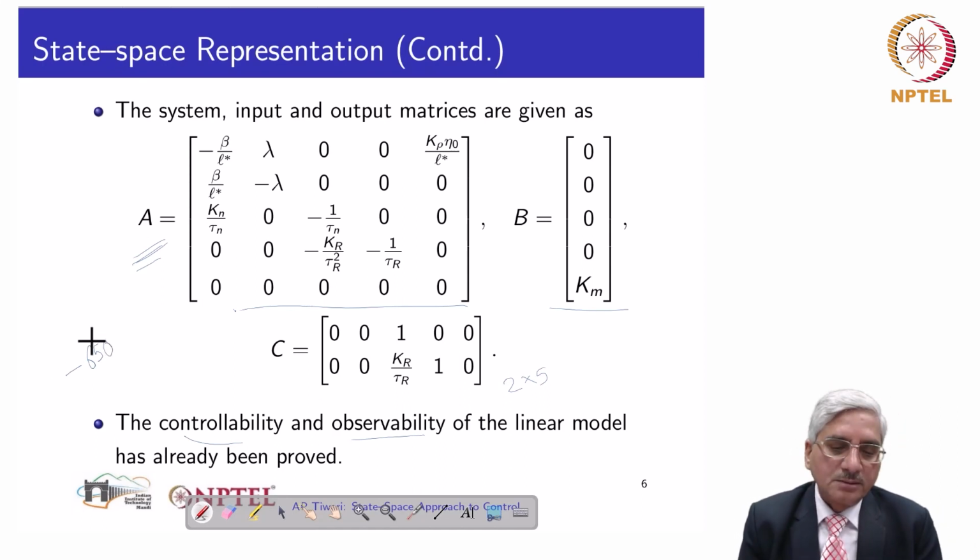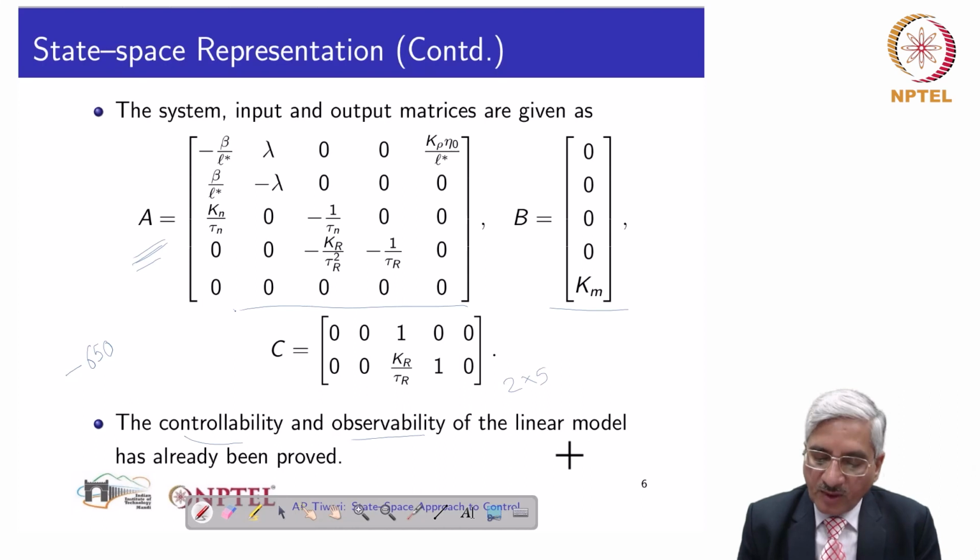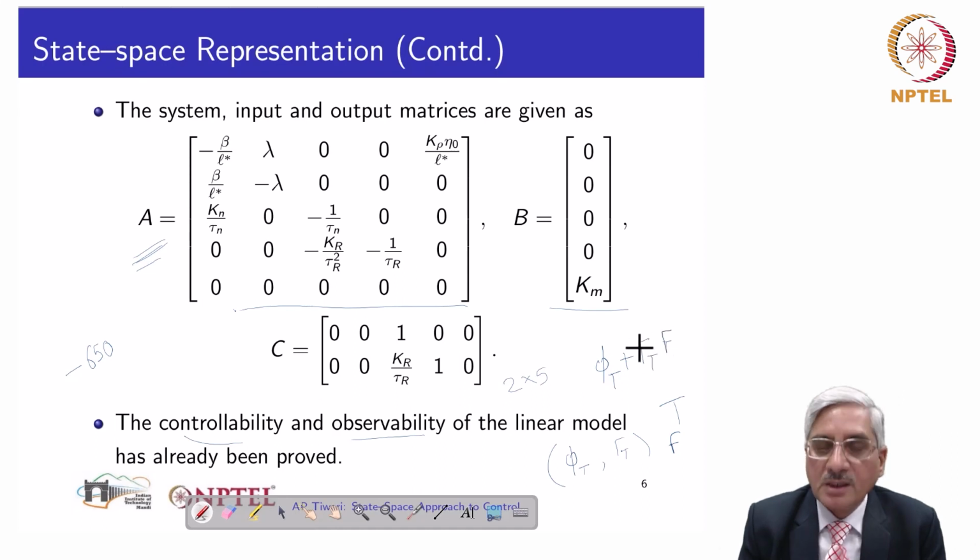Second thing is that an important consideration in the design of fast output sampling based controller is that we are required to design a state feedback for the system phi t gamma t, which is the discretized system for AB corresponding to the sampling time t. Now that with the state feedback F for the system, this closed loop system phi t plus gamma t F, this closed loop system matrix should be invertible.